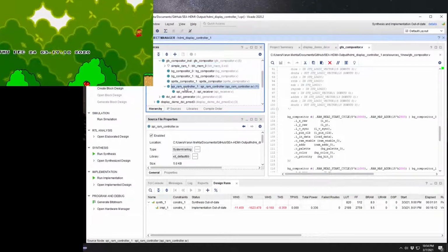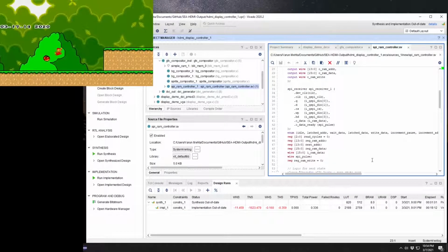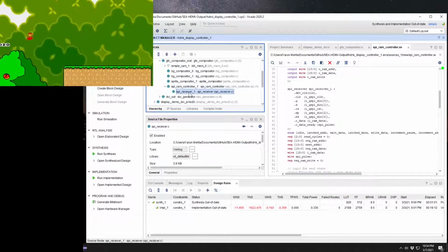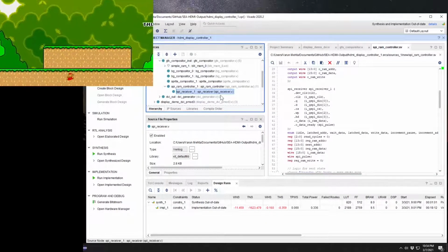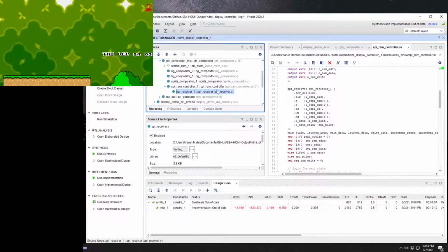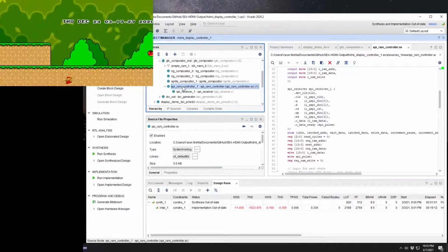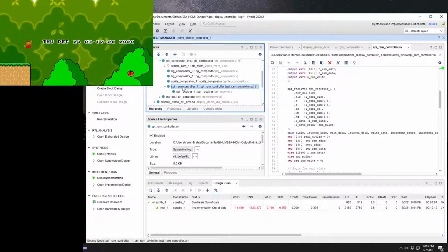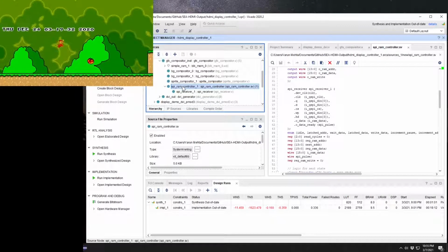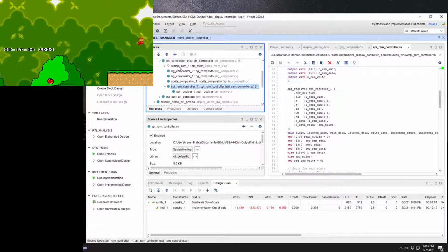So diving in a little deeper now, the SPI-RAM controller. I won't belabor this because I think some things may need to change, but basically the design here is that there's a SPI receiver, which is what actually is getting the signals from the ESP32 and interpreting those SPI signals into data. The SPI-RAM controller then receives each of those blocks of data in the form of 16-bit words and knows which RAM address each of those words should be shared with, and then this SPI-RAM controller is what is connected in to our RAM.